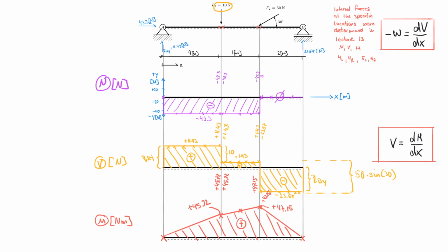But please understand that conceptually it can help you to think that this is the integration of the shear force. So the moment is the integration of the shear force, but you have to treat that with caution because sometimes you have integration constants. One last word about the moment here, and another thing that we can use to really validate our results. Notice that everything here is a positive moment. And that makes perfect sense if you think 1 or 2 lectures back when we actually defined how our internal forces are really properly arranged and properly defined.